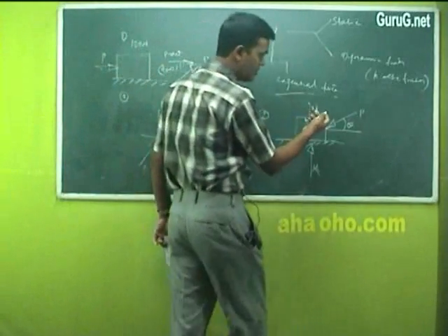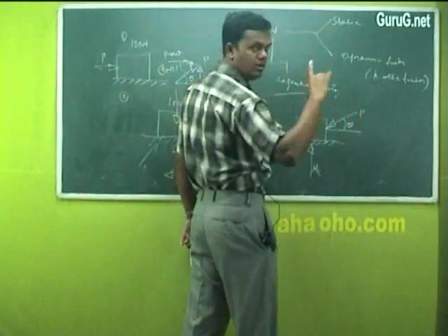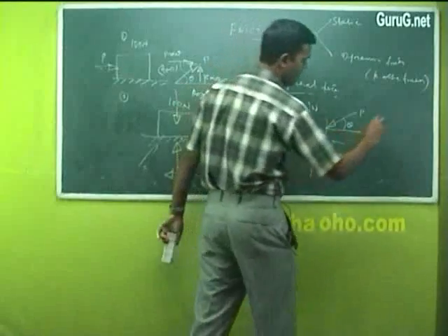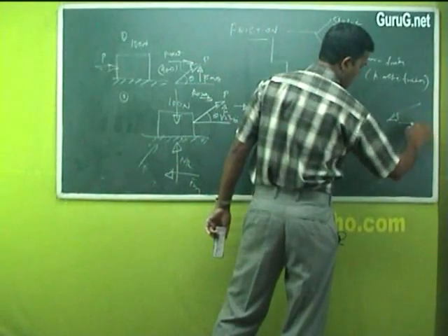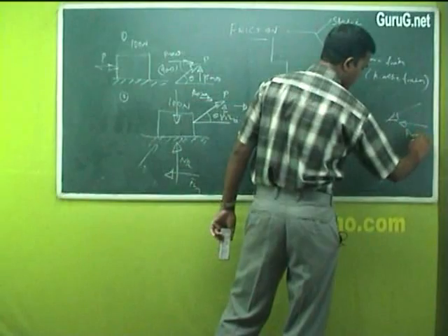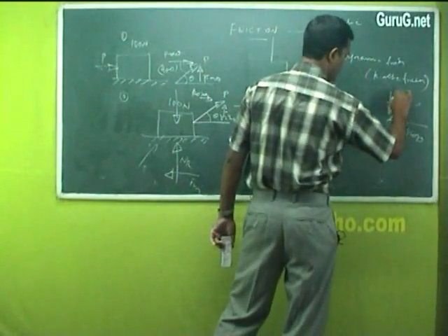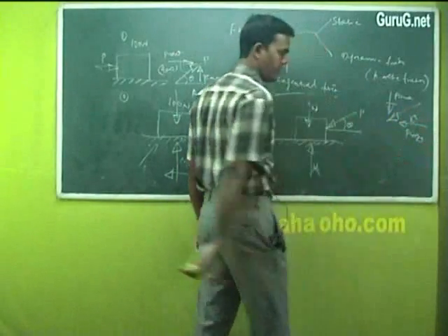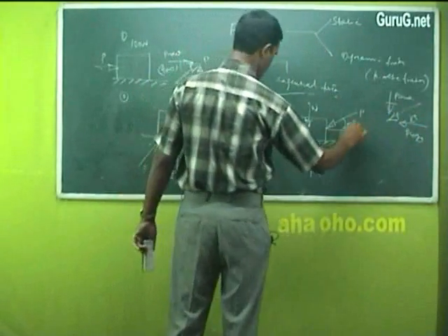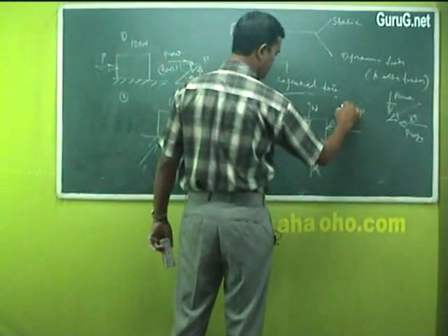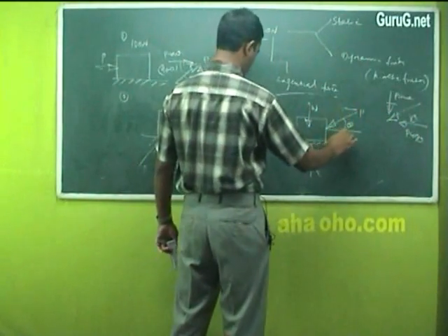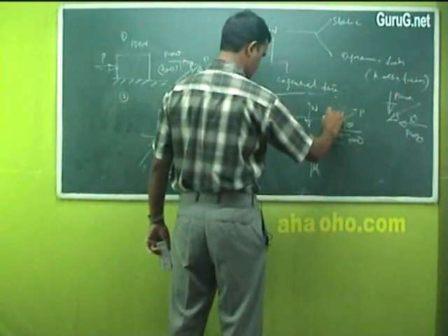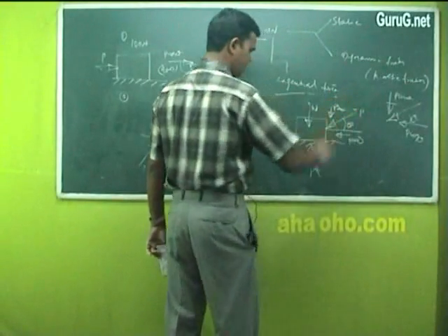And here, what should I write now? I am going to resolve the resultant value into two components. How is that? One is P cos theta again, and this is P sin theta. Again the angle is here theta. So the same thing, I can show like this, or show here, P cos theta comes here, and P sin theta will be opposite side.